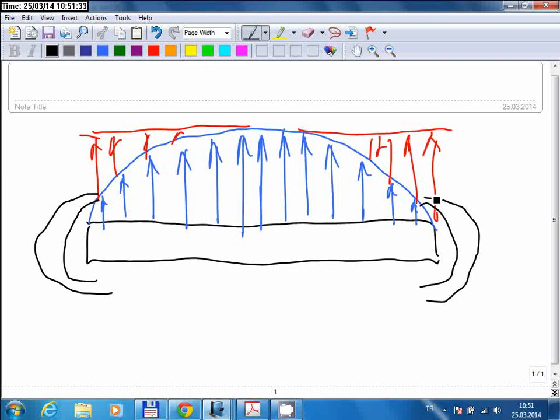So one way to do that is to use winglets. That's why the aircraft manufacturers use winglets. And if you think about what a winglet is, you basically put a blockage here, right? If you put something like this, that's how a winglet looks, or it can extend on the lower surface as well. Then these parts will prevent some of this flow here, and that will be reducing that. But this phenomenon, these wingtip vortices,